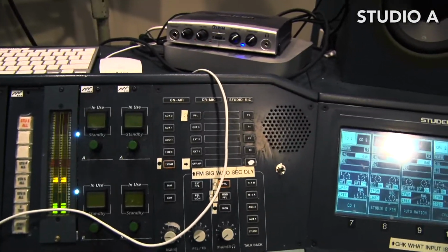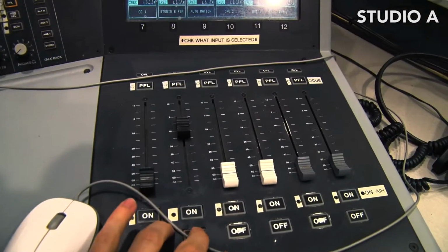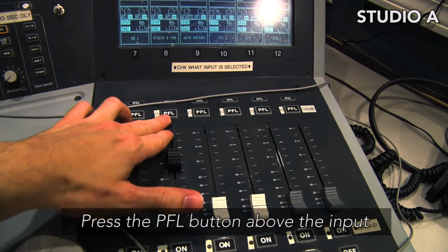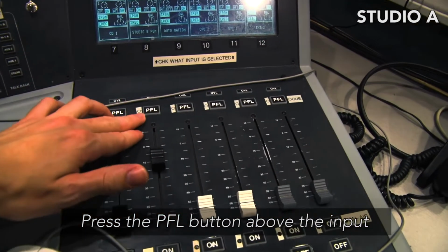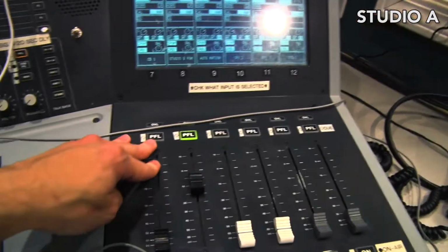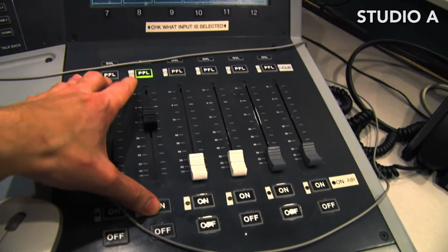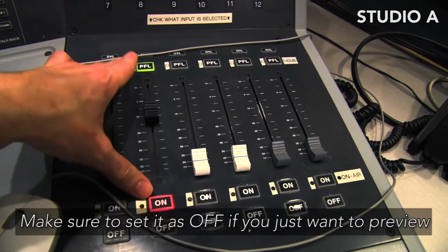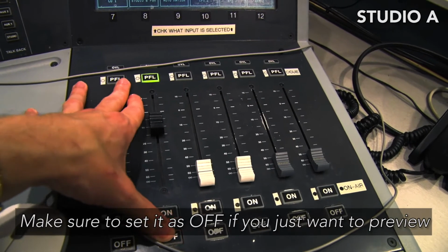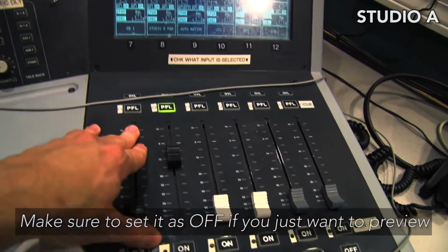So there are two ways to PFL. You can have the track off, and there's the button up above each input that says PFL. Hit that, and it's green. Green is good. It means you can listen to it, but it's not going to air. Red is danger. That means it will go to air. These can be on simultaneously, but this will still go to air if this is on. So make sure that's off if you just want to preview.